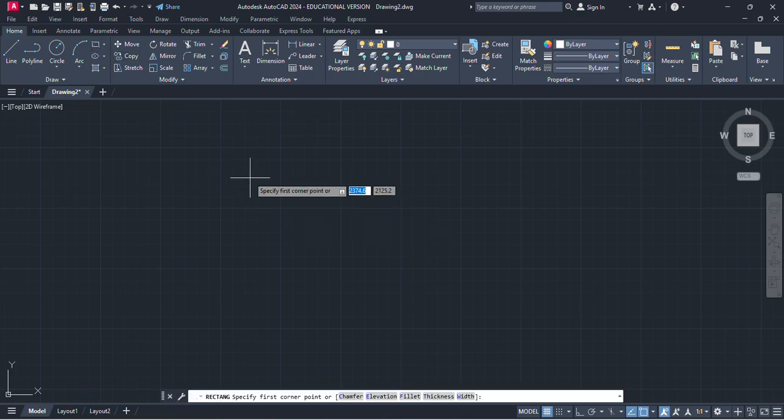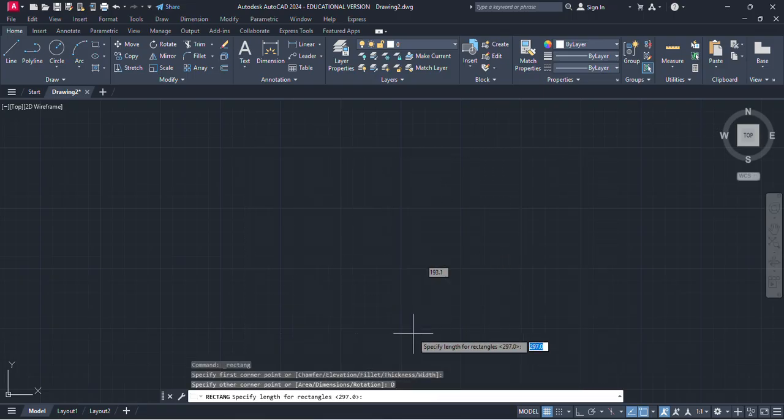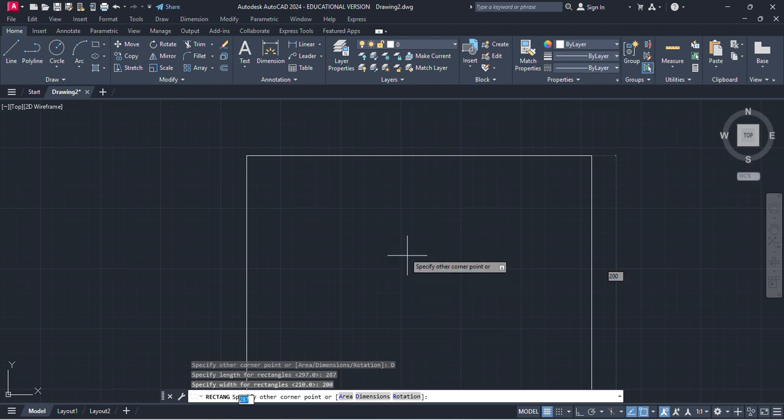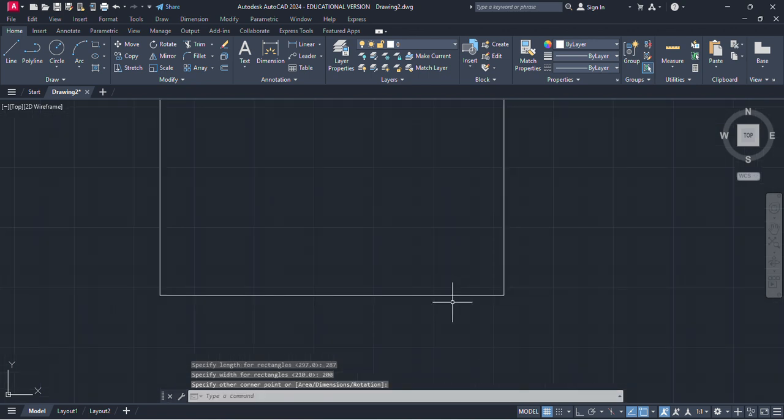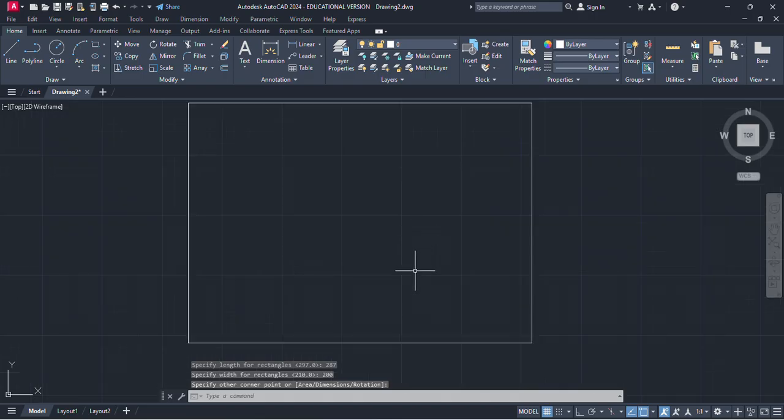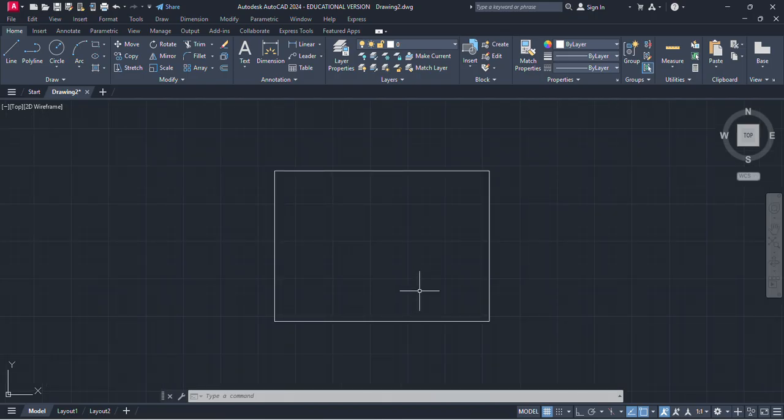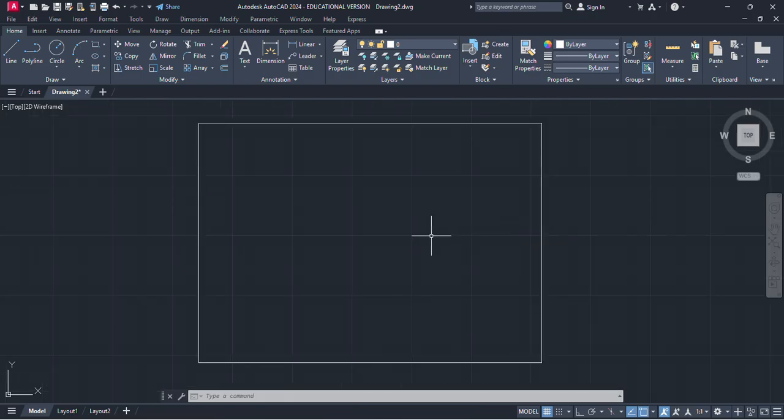This rectangle is going to be 10 mm less than the original: first point, then dimension. After applying the 10 mm margin, it is going to be 287 by 200. This is our A4 sheet with 10 mm margin, in which we have to plot our point A.